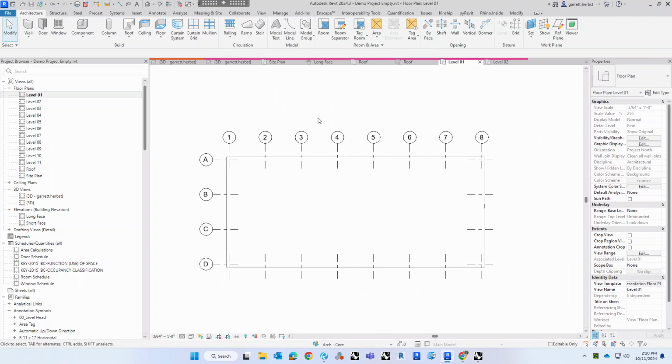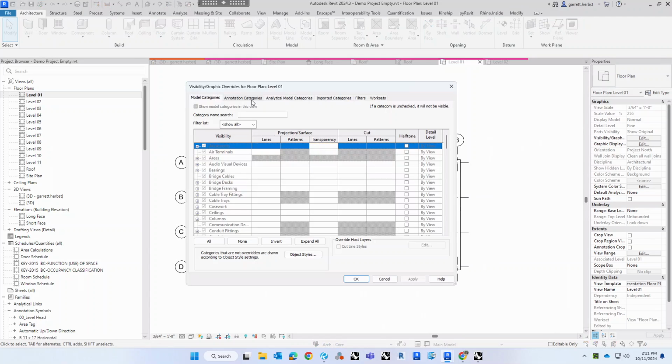So I'm sorry, you set the square grid, but it wouldn't be square, right? That's the structure. More rectilinear. I mean, it totally depends. So 30 by 30 is the max grid size that we typically use. It's also one of the most typical grid layouts for offices. So a lot of office furniture and all those systems are designed around that kind of grid system.